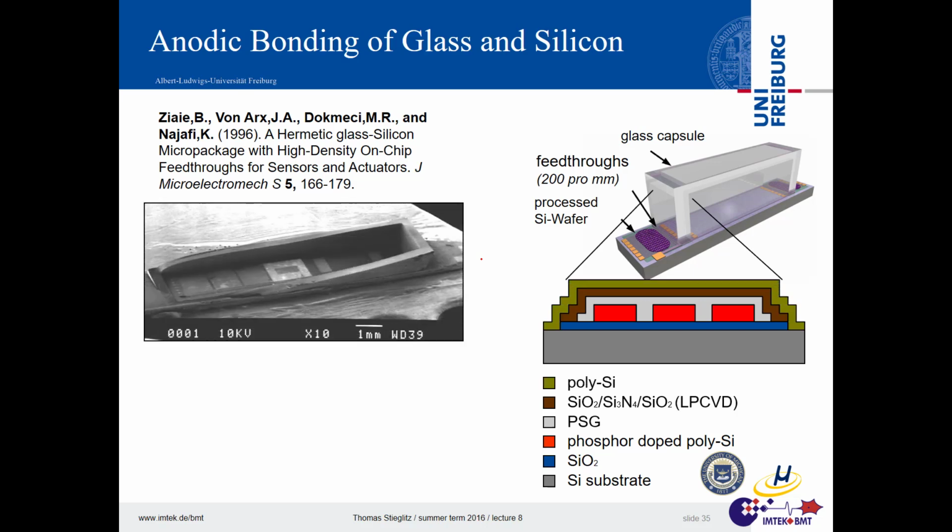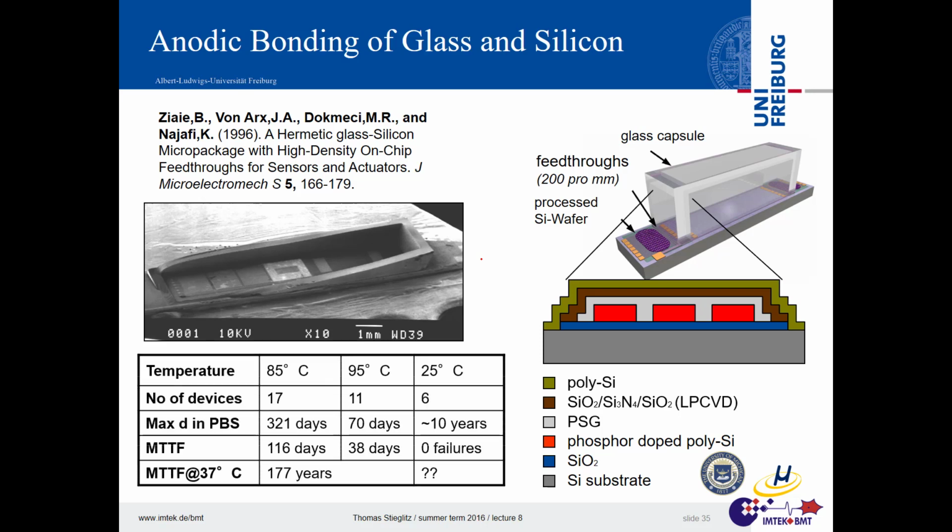They wanted to speed up a little bit, and then they took a chisel and tried to remove it. And the good thing here is that this is a cohesion break. It means the adhesion interface between the package and the substrate stayed stable, and they completely destroyed the package wall. That is a good outcome in this case, because their solder link survived. They did some accelerated aging here, and with a mean time to failure of 177 years, this is a good result, but I would immediately get suspicious if I get something like that. That's too large to be true.